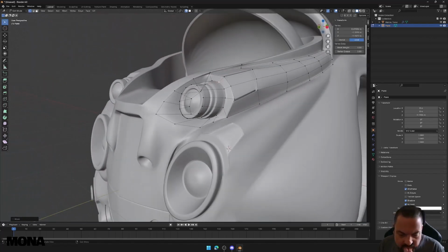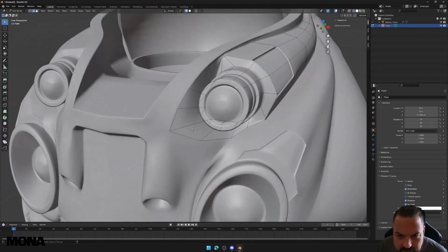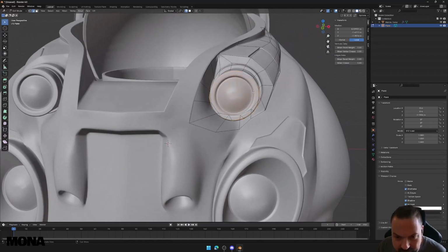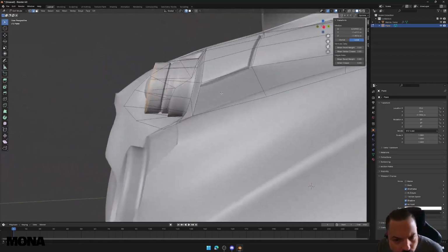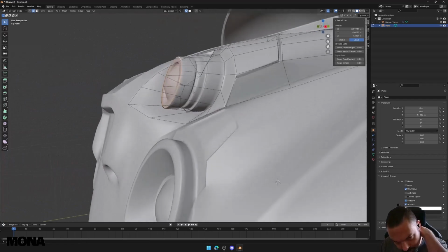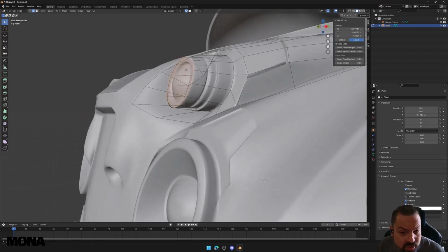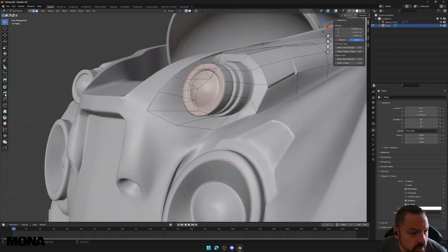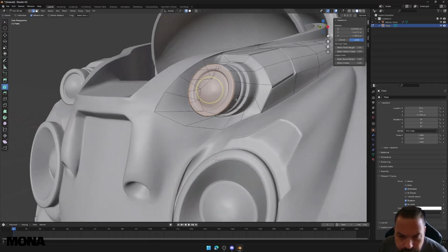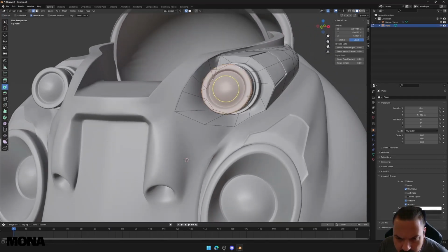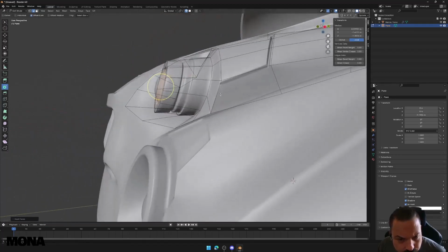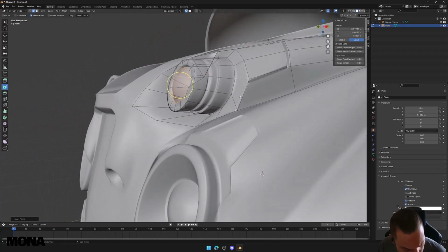So yeah, engineering and reverse engineering at best. So let's do that. Let's press F to close that off. Now I want a little bit of that. I don't want to go in because that's too many polygons and you'll never see that edge, right? So I'm going to use inset. And I'm going to go, oops, no, go down to maybe there. Maybe even smaller.